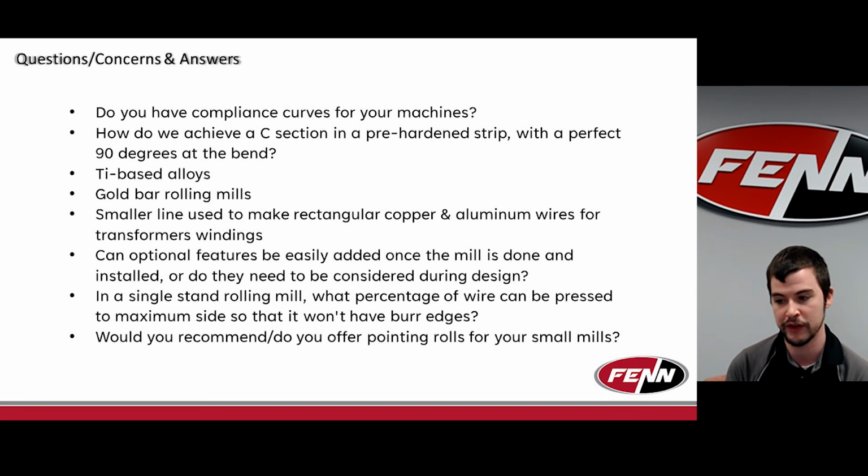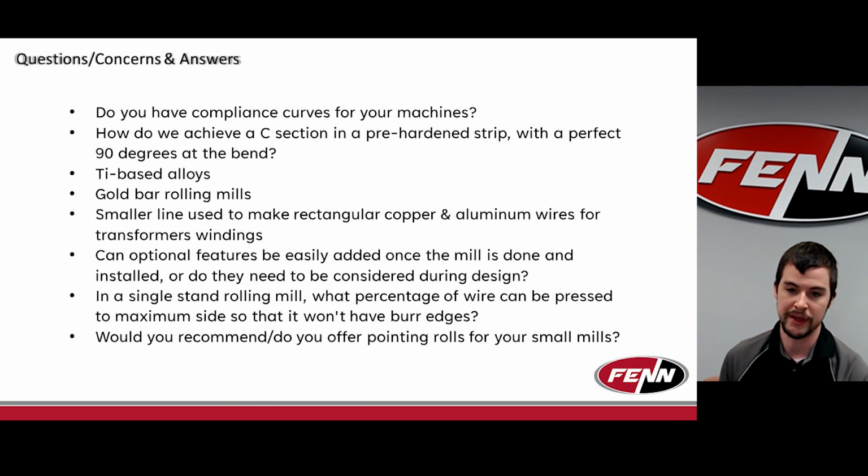And then when you're trying to clean up those edges, in order to create your corners or your radiuses, what often leads to generating burrs is the overflowing of the material into the cavities of the profile that you're trying to make when it comes to shaped work. With rod rolling or things like that, you also can risk creating burrs. That basically comes down to taking too large a hit metallurgically, so that when your material wants to flow, it has nowhere to go. Thus it pushes back too much on the open cavities in the roll geometry, creating those sharp edges.